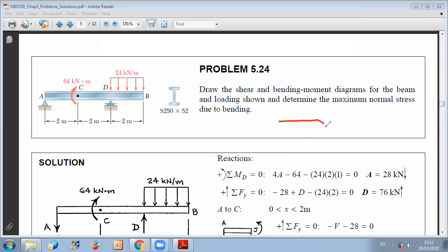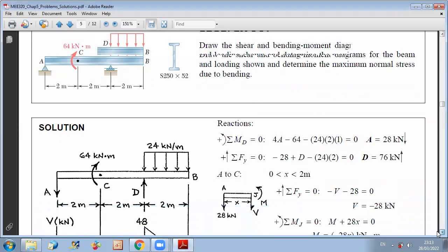However, when you take two parts of beams connected through a hinge, each part is in equilibrium if you do the analysis here. Then you consider that this is at the extremity of this part, and the bending moment here should be equal to 0.